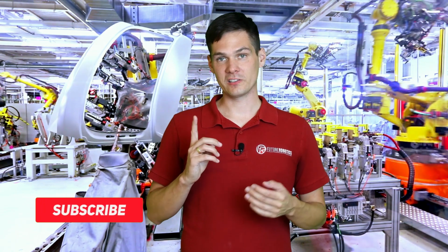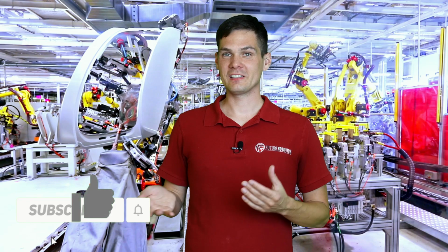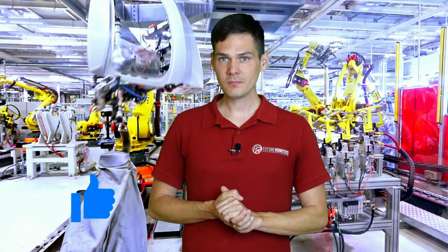Following that topic, you'll say, okay, we also have handshakes. Yes, you do have handshakes, but again, the same rule. If something goes wrong on the PLC side and it lets the robot in for any reason, then what's going to happen? The other robot will come in. So you should use the collision zone anyway. You can say it's double safety. I think it's better to have double safety than one chance of crashing the robot. So it's always, like we say, better to be safe than sorry. That's pretty much it about the collision zones.